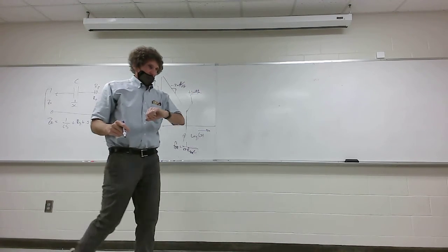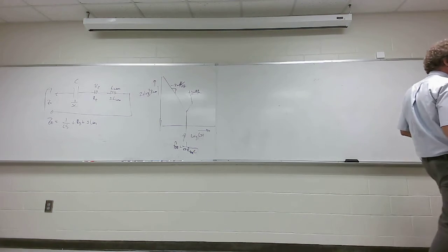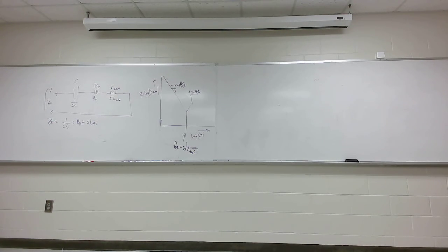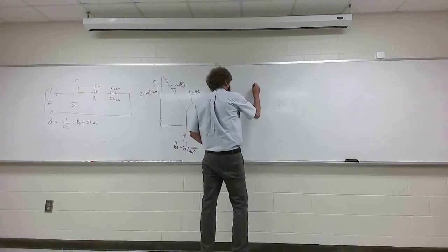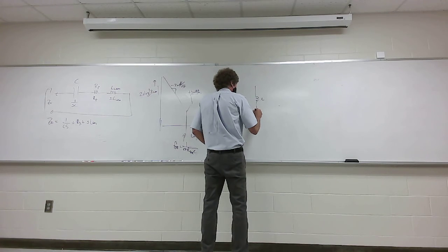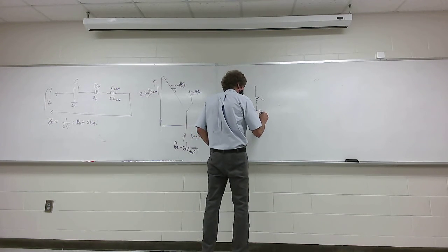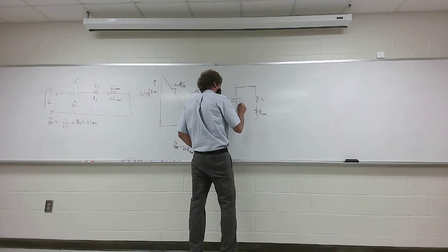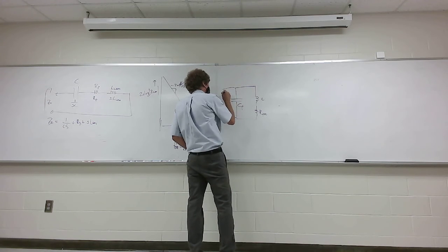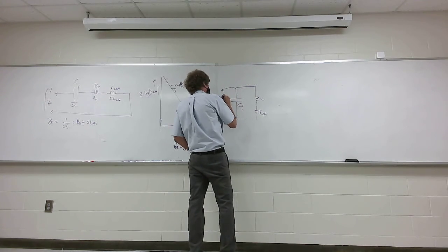Now, I don't have time for this, but in his book, he talks about the inductor model. Inductors can be modeled all sorts of ways, but I just want to tell you his plot of the way an inductor looks, on the bottom of page 511, is correct. So he has an inductor, the actual inductor. Then he has the resistance associated. This is R parasitic, or R unwanted. And then he has a capacitance across here. It's a parasitic capacitance. And this would be Z in of the inductor.